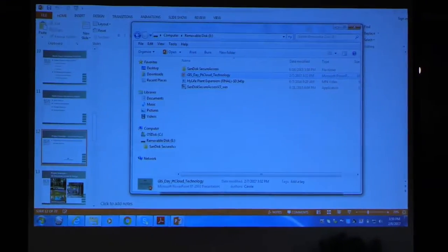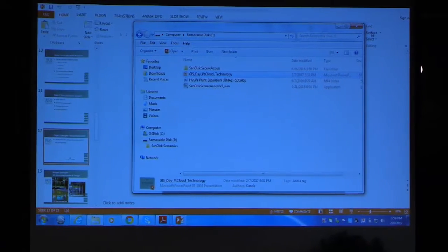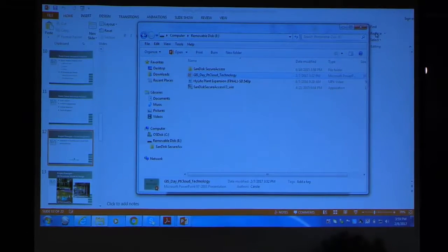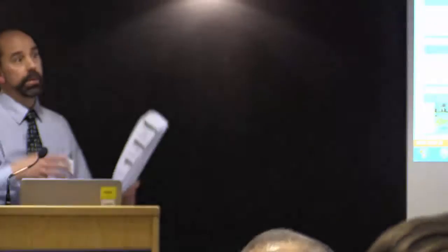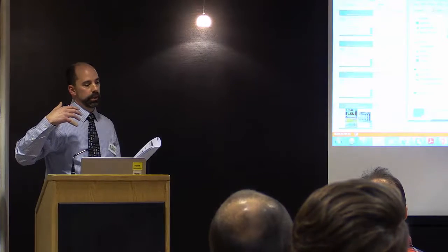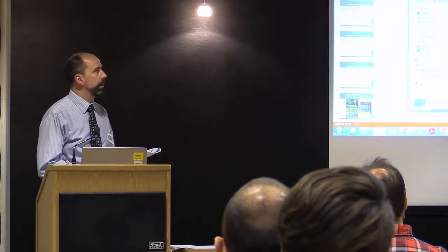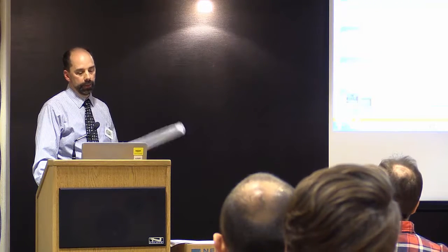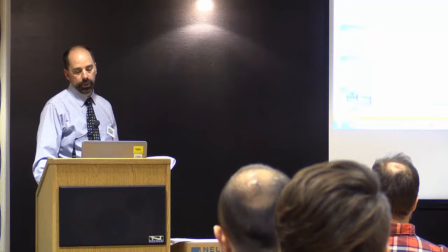So this is an example of point cloud integration fundamentally. This is a project we did where an existing structure and facility needed to be expanded upon. So it included additional structures, additional parking, additional piping, and all the other related engineering work. So we, through a combination of LiDAR, imagery, 3D scanning, conventional surveying, converted this point cloud data to a 3D model, a solid object model.